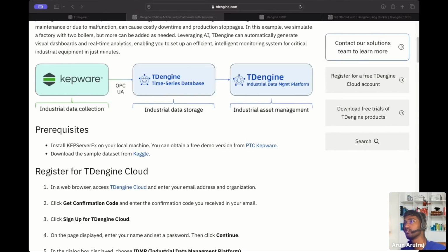But before that, let's go into a little bit of detail about what exactly OPC UA is. OPC UA stands for Open Platform Communications Unified Architecture. It's a vendor-neutral standard that defines how industrial devices are able to connect in a structured way. It's platform independent, so you could be on Windows, Linux, or Mac, it doesn't really matter. And every data point carries context, so it's a model-based design, right?